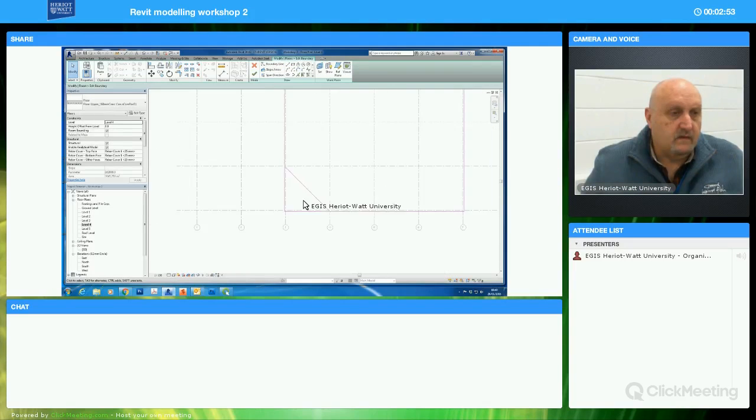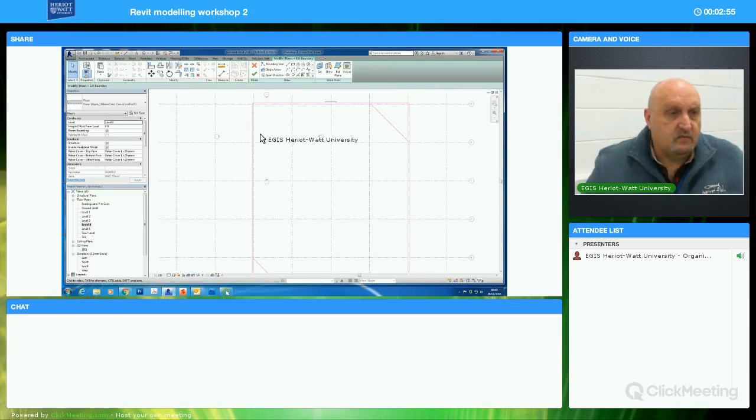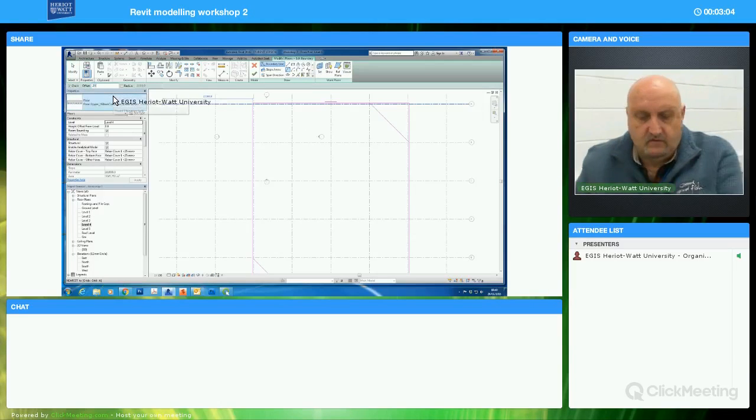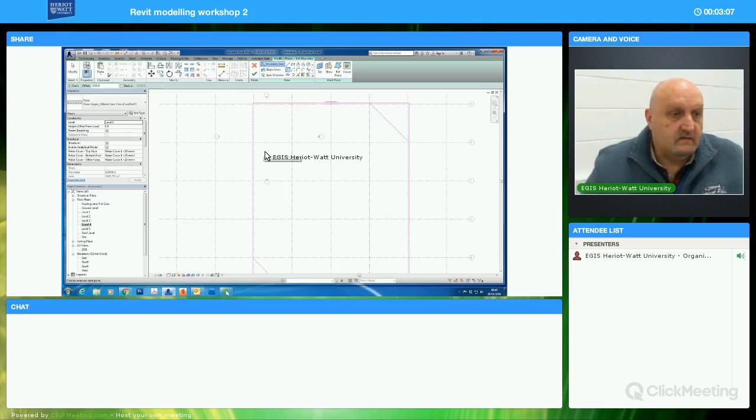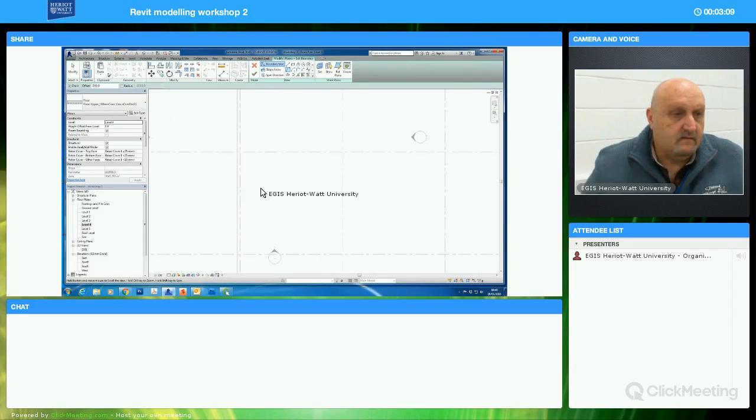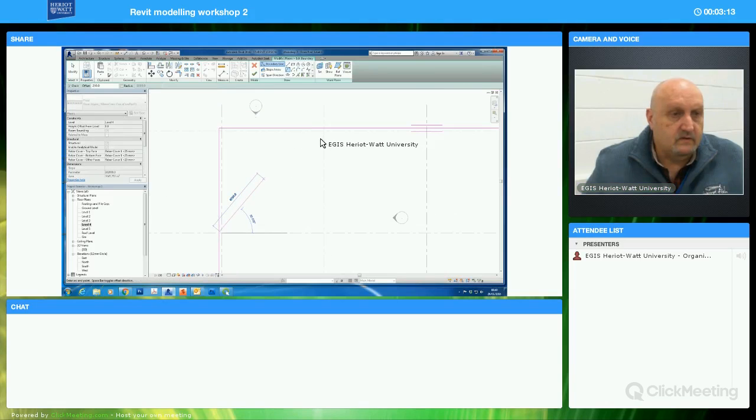Okay. And then on these two corners, I think I'm going to put arcs in, just to give it a kind of filleted corner. Now the arc tool is in here. And again, 250mm offset. And yet again, it's the intersection here that we use. You'll see that it will snap to the tangent there. I don't know if you can see it snapping. That's not me clicking, that's just it snapping. So when it snaps, then I click, and I'm happy with that.